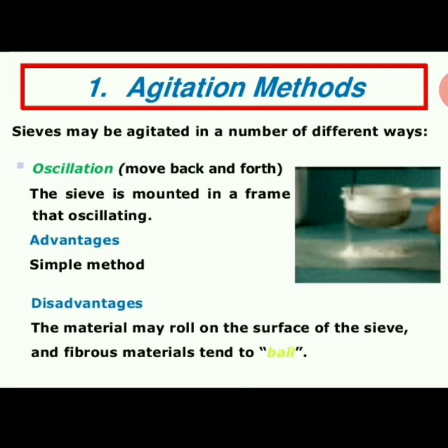Also, the second disadvantage is that if the powder is not dried, meaning it has a lot of moisture, then the aperture becomes clogged with the particles, leading to improper sieving. Meaning, if a powder material has lots of moisture present, it will not pass properly through the sieve, and the openings of the sieve will be clogged and proper size separation will not happen.